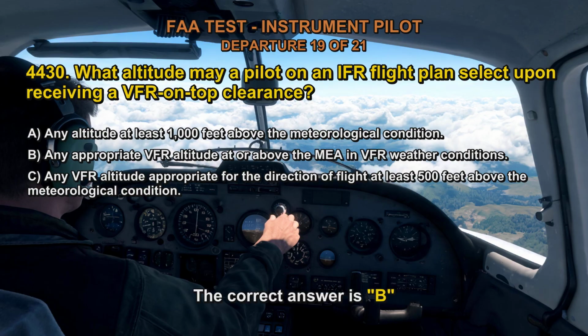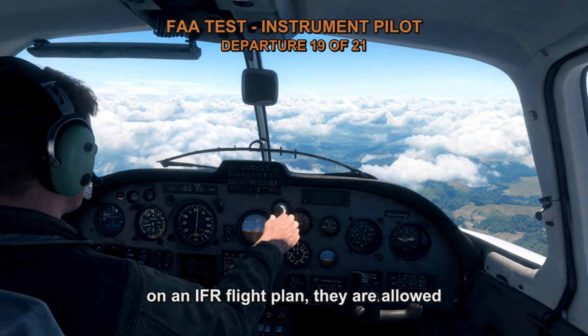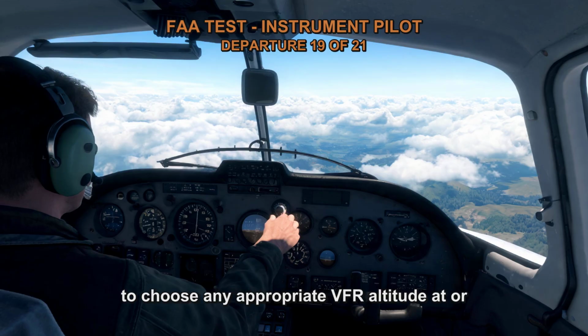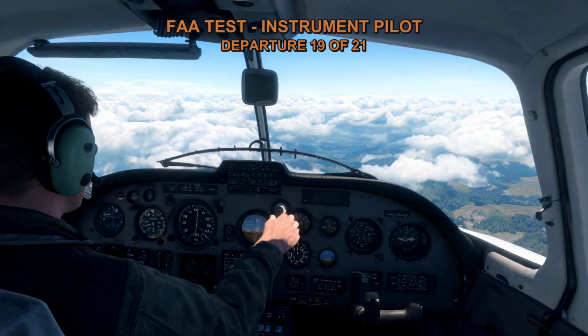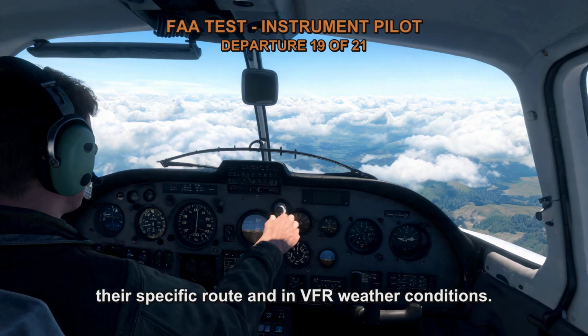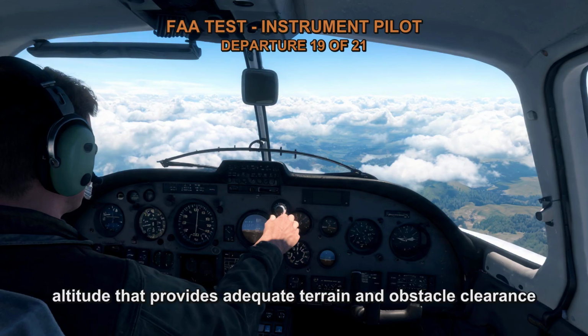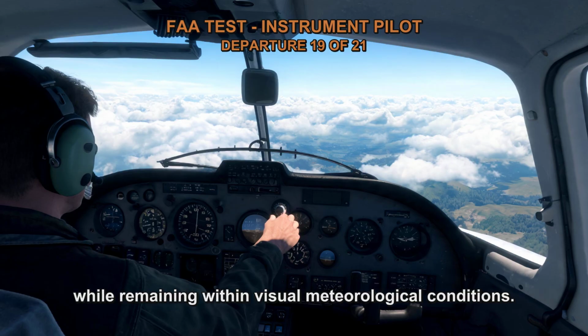The correct answer is B. When a pilot receives a VFR on top clearance while on an IFR flight plan, they are allowed to choose any appropriate VFR altitude at or above the minimum en route altitude, MEA, for their specific route and in VFR weather conditions. This means that the pilot can select an altitude that provides adequate terrain and obstacle clearance while remaining within visual meteorological conditions.